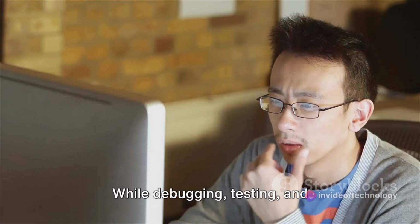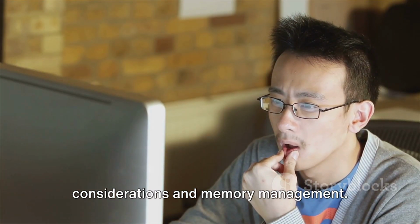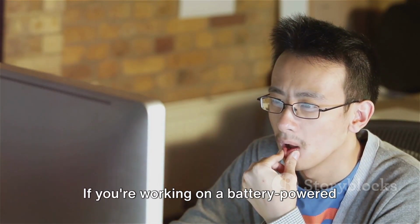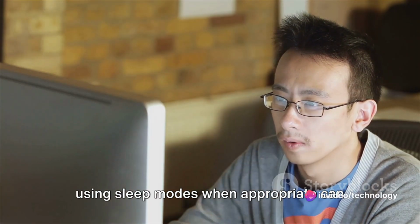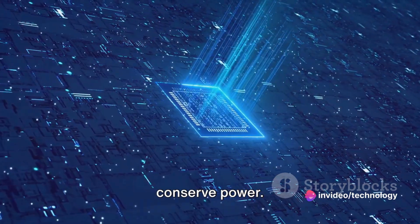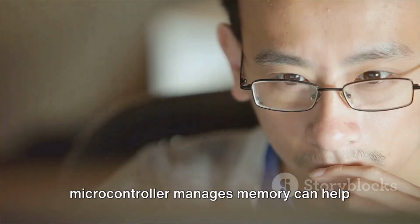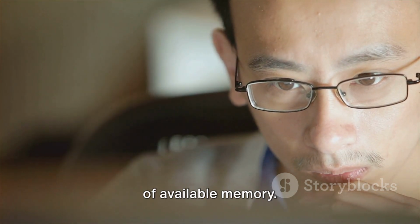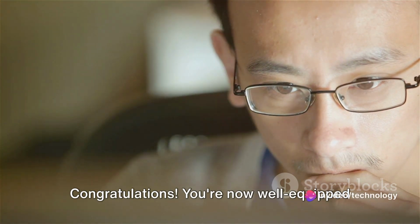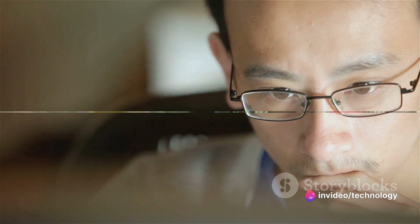While debugging, testing, and documenting, don't forget about power considerations and memory management. If you're working on a battery-powered application, optimizing your code and using sleep modes when appropriate can conserve power. Understanding how the 8051 microcontroller manages memory can help you optimize your code for efficient use of available memory. Congratulations! You're now well equipped to program an 8051 microcontroller.